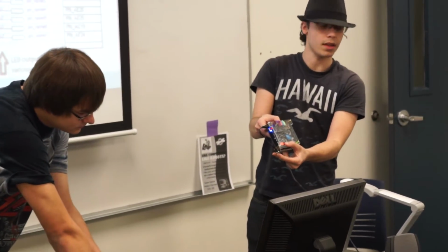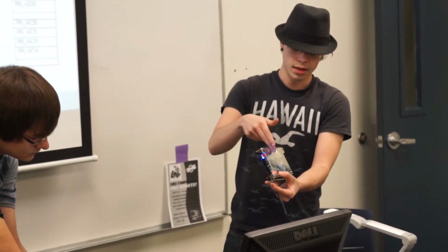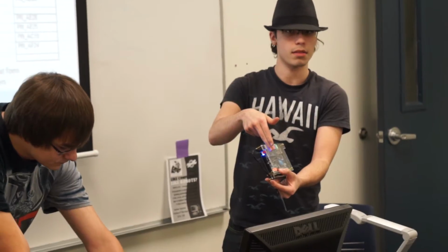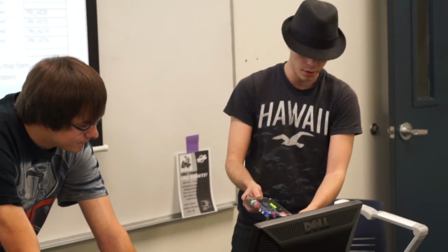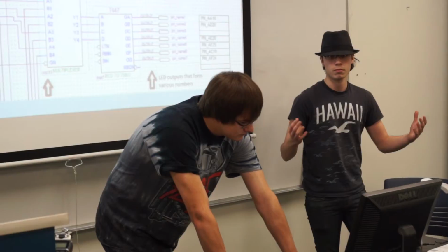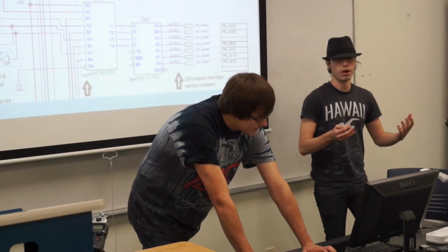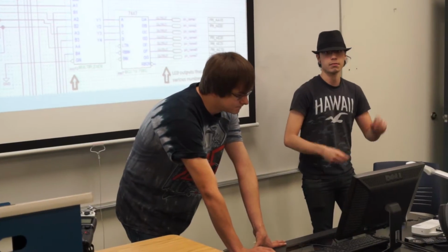It would go up to 9, then clear, going back into our 1 second pulse driver, and then pulse the second tens place of the decimal for our seconds forward 1 up to 60, where it would roll back over to 0, sending a clear signal to clear the seconds driver itself, as well as sending that signal to power our minutes forward 1 minute.